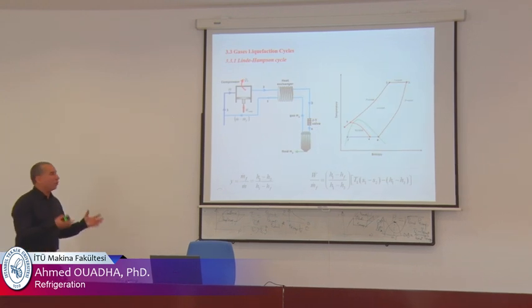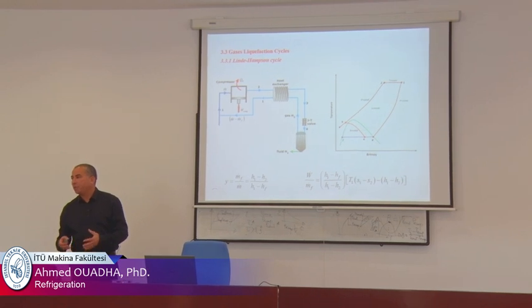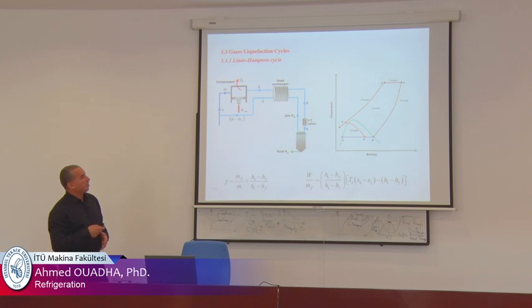So the other group of systems used for the liquefaction of industrial gases, like nitrogen, hydrogen, oxygen, are gas liquefaction cycles, like the Linde-Hampson cycle here, which is simply composed of a compressor, heat exchanger, and here a flash. Generally, in this type of cycle, there are two parameters to take into account: the quantity of liquid obtained at point 4, and the work consumed to drive the compressor. So the interest is to increase Y and to decrease W, using the concept of the Joule-Thomson expansion here.